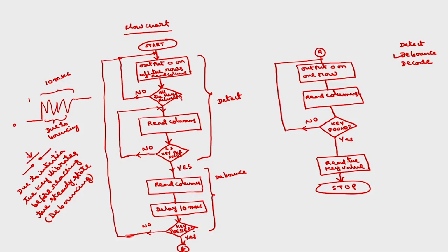Now if I know this flow chart, I can map this flow chart onto the assembly language program. So here I will write main program as well as subroutine. For that the program will be: initially the setting is, because we are going to use the subroutine, we have to initialize stack segment. Data segment is anyhow necessary. So we take some contents into AX, 5000, move DS comma AX. We are setting data segment register to 5000, means the starting of the data segment will be 50,000 H.